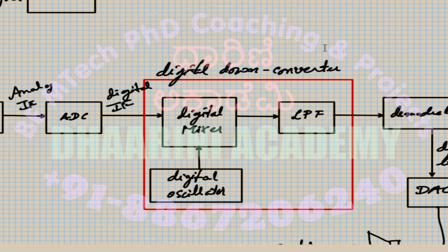You can use varieties of DSP algorithms as well to make modifications in the radio wave output. That is possible if you use the software part. That's why the SDR type of radio transmission became more popular. You can control it on the software side itself, because if I want to change from AM to FM on the hardware side, you have to change the complete circuit.